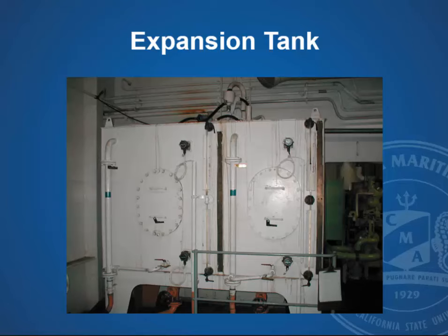And typically you should only be adding water to that expansion tank at a very slow rate because of any evaporation, which is usually pretty small. Most chief engineers will have a clipboard or some method of providing the assistant engineers a way of recording each time that you add water to the system and how much. The reason you're doing that is so that if there's any leakage in the system, you will have a way of determining this.